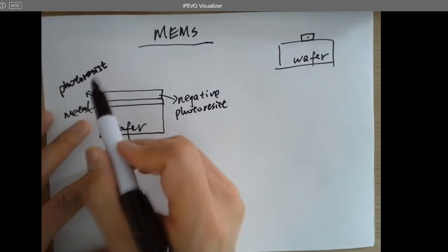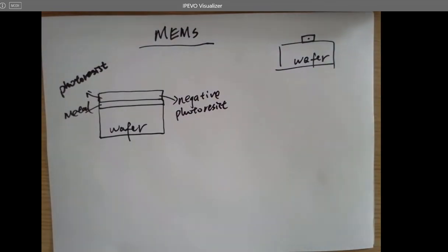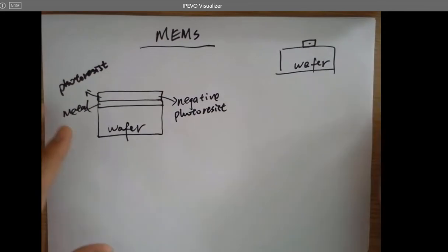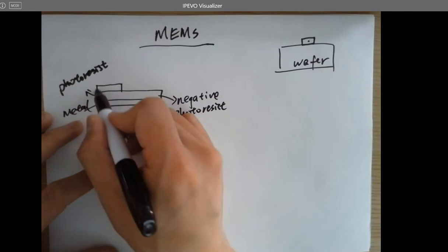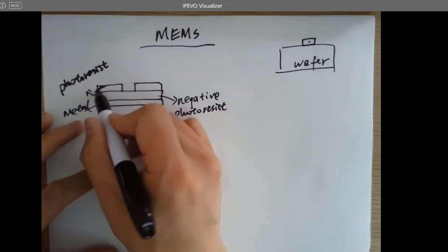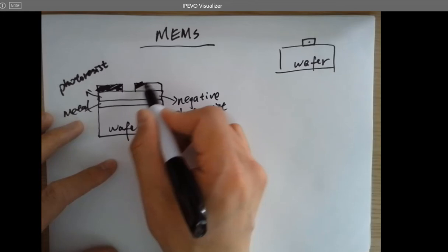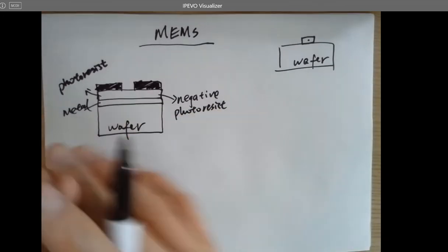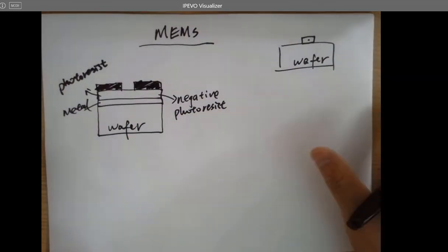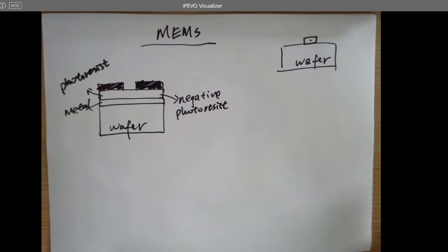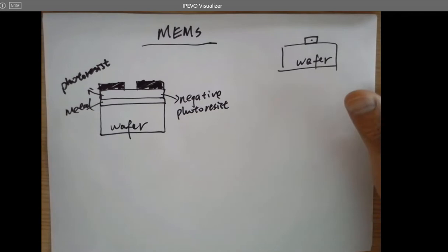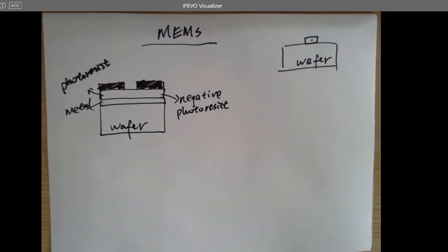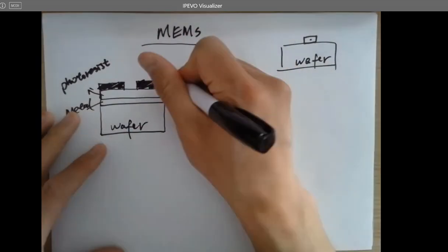Then I need a mask, so you can design the mask. So now it comes to the mask, right? You can design the shape or the feature in AutoCAD. For example, you can draw a line to make it transparent only here, but all the other areas of the mask are opaque. The mask is just a simple sheet, it can be a plastic sheet, or something printed on a glass plate as well. I think the semiconductor industry uses glass plates instead of the plastic sheets we use. So that's a photo mask.